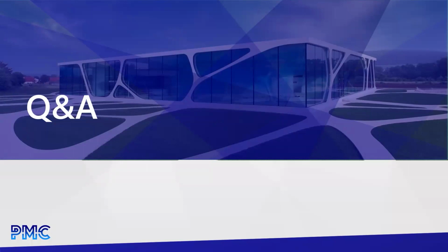In the case of snow, again, a little bit of snow is okay, but the scanner will scan the snow. And so if it's a heavy snow, your point cloud can become unusable because the scanner scanned a ton of snow and you can't actually find the building wall anymore, because you've got points all the way through the space, which is open air but was filled with snow.